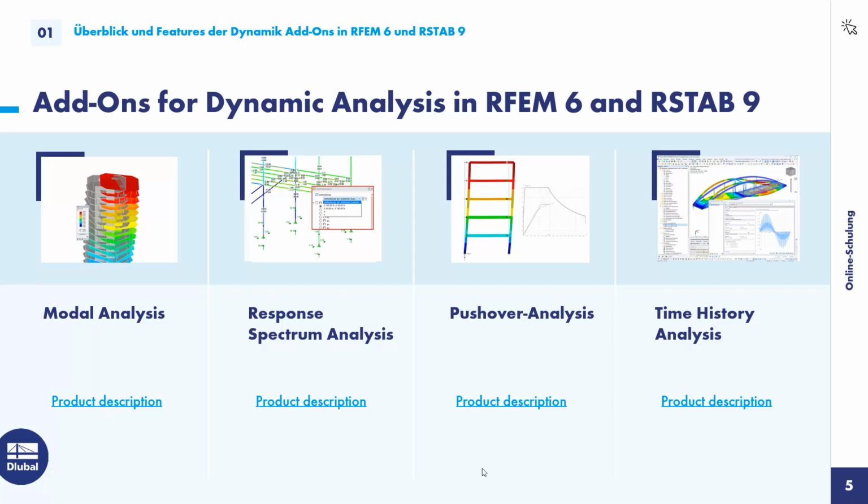Then in the last slide here, we also have the time history analysis. This is going to be the topic of today, so I won't go into detail right now. There is a differentiation between the linear time history and the nonlinear time history. We will look into the linear time history, since it's just a simple vibration analysis and we don't have to take nonlinearities into account.